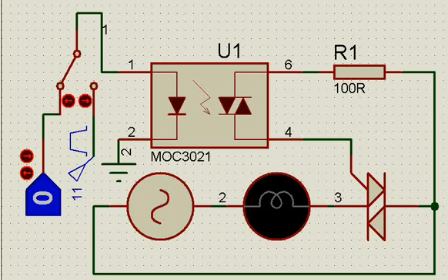Hi, welcome to this session of understanding how the triac is used in combination with an opto isolator, and particularly a LED and diac combination opto isolator. They are termed as MOC 3020, 3021 and several other numbers, and they are non-ZVS type opto. Non-ZVS type opto means it can switch on not at the 0 but anywhere the triggering is made. We will see that with this kind of arrangement.